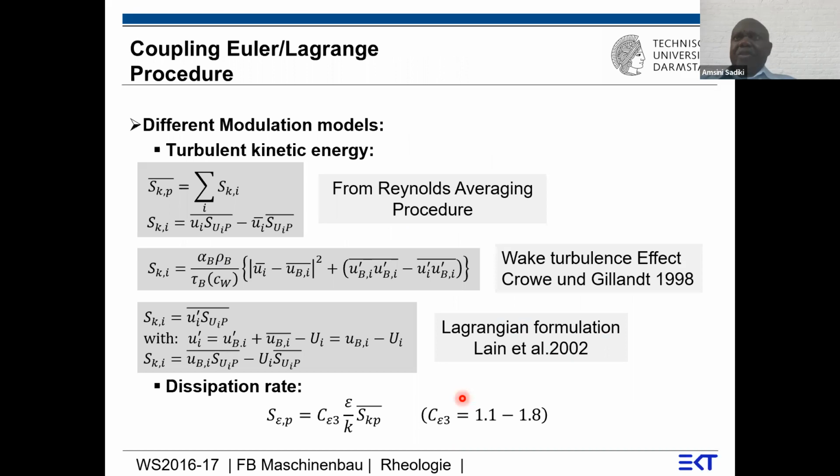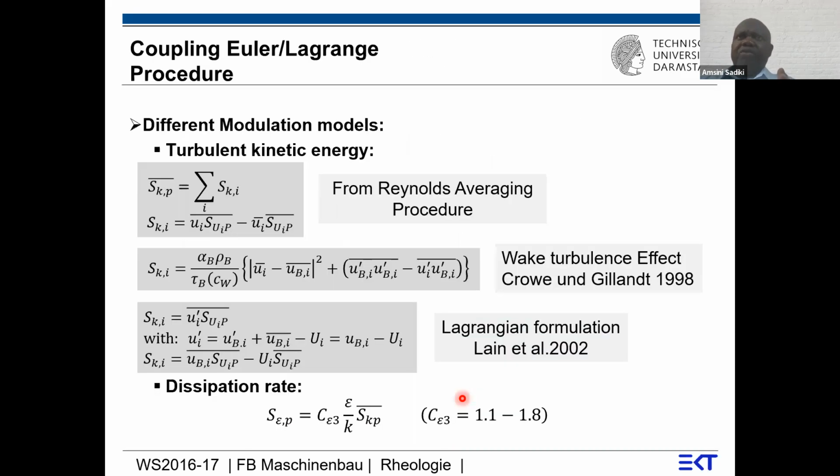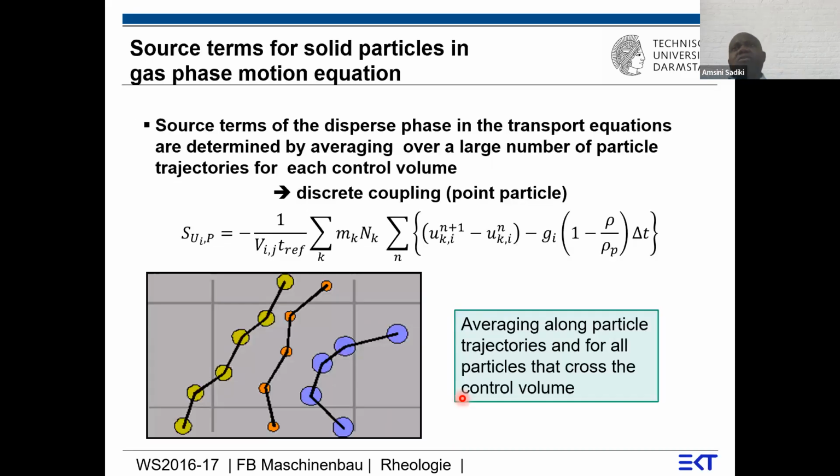And now we have to deal with the different source terms we obtain here for the momentum. We have to obtain also for the k-epsilon. And for k, it is not very complicated. So we know that to obtain the turbulent kinetic energy, we have to make a scalar product of the momentum equation with the velocity. And from this, we can obtain a kinetic energy equation. This is what we do here.